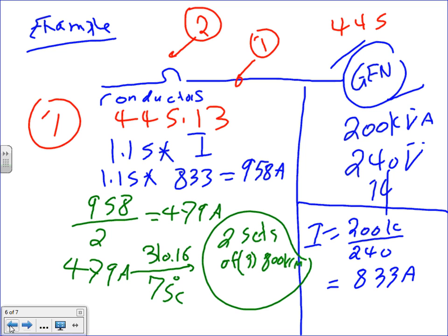So I want you to understand that what we're doing here has nothing to do with protecting the generator. The generator has its own full protection that comes with it: overload, over frequency, short circuit, everything. The only thing we're protecting with this overcurrent protection device is our cables. That's why I size the overcurrent protection device to the cable. This is by code. The overcurrent protection device can be any value you want as long as you protect the cables. Any questions, guys?